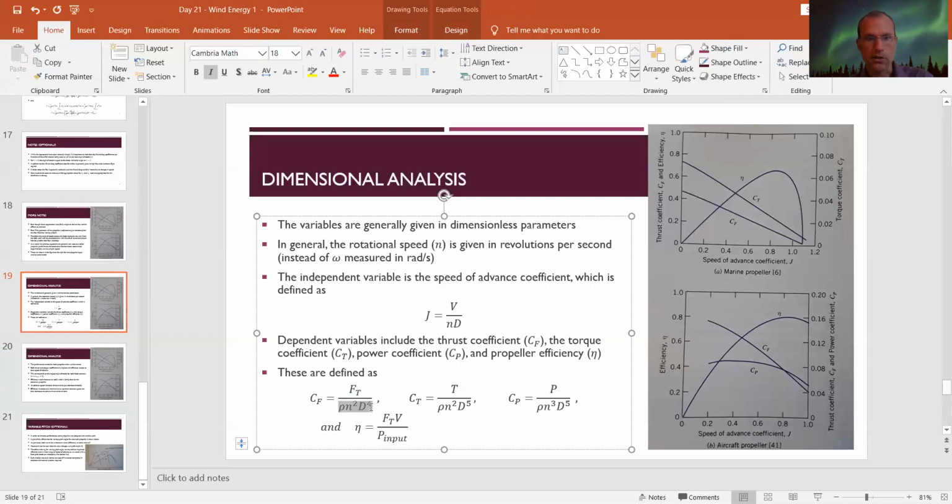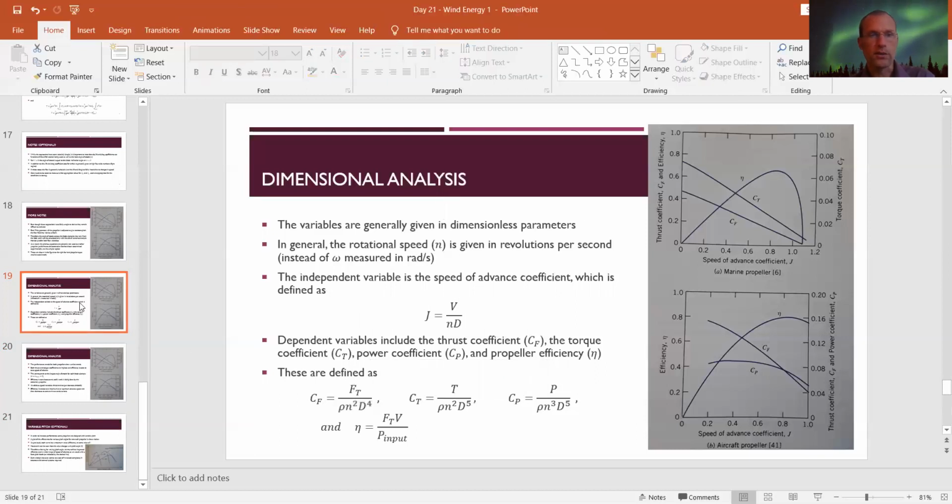I know all these values down here, so I solve that for my force of torque, and for my force of thrust. And at that point, I can find force of thrust much easier than trying to figure out how all this stuff depends on the angles and do those integrals. So generally, this is how it's done using these graphs.